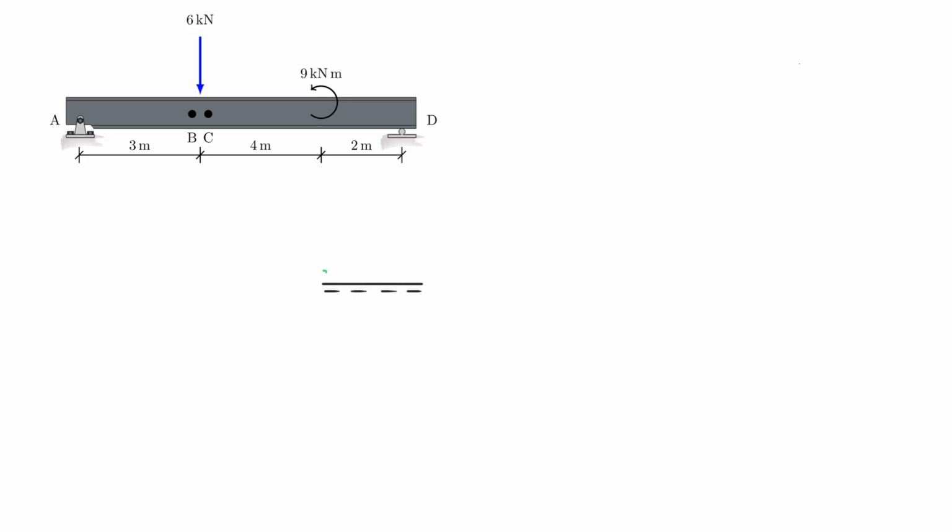So now I'm cutting right here. And my support reaction now has a value of 1 kilonewton here. I will bring in the other side of the cut, now that I flipped it in half, and you will find that the moment goes in this direction, shear force in this direction, and the normal force in that direction. This would be at location 7 meters to the right.